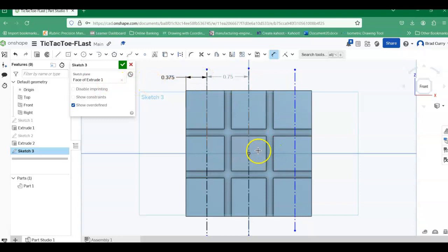That is because we kind of picked up on the center point in the plane and used that in. So this is what we call basic dimension. It already knows that because we have constrained this construction line to our center line of this part. So let's go ahead and create another dimension from here to this construction line. So we're going to make this 0.75 as well, and that's going to bring it over. Notice again the difference here in the way these dimensions are shown.